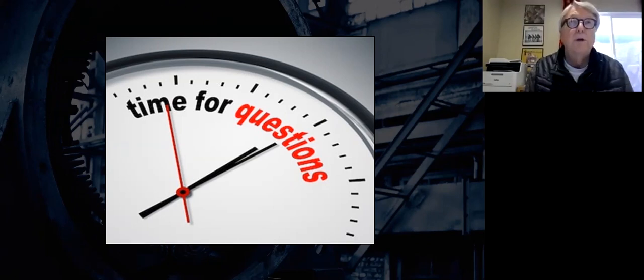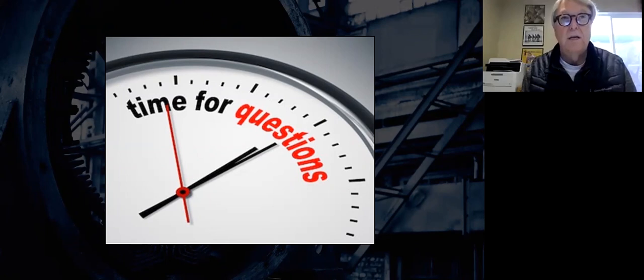So all you need to do is change the transformer size, and then that probably means that you added a new switchboard. So you just add those two things to your existing database. Boom, you have the computer, and it takes 2 or 3 seconds, and then you take a look at it, and if it has changed the arc flash, which it will have pretty seriously, then you need to put more stickers on. But it's a lot easier than going through and doing that first arc flash study.